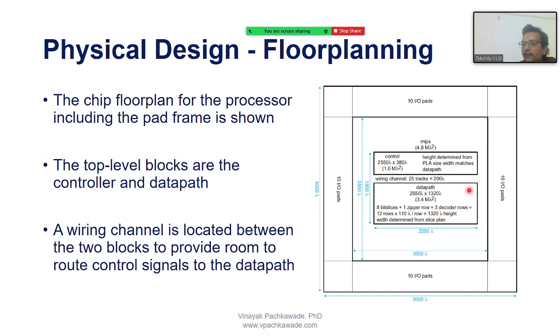By hand calculation, like I taught you with the lambda rule, they will already know the size of that unit cell, and using the unit cell they will keep calculating the higher blocks that they are putting in the area, and finally they would estimate the final size of this architecture as written over here.